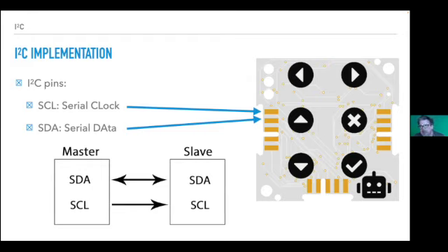So the clock is not necessarily all the time just going up and down. There's also sometimes a signal over the clock to tell the slave what to do next. But in general, it's just a clock that goes up and down. And then through the communication between the slave and the master, they then agree on who has to talk. The master actually tells you if it expects data from you, and then you talk at that point. And once you have spoken, then the master takes over and you wait to be asked again.